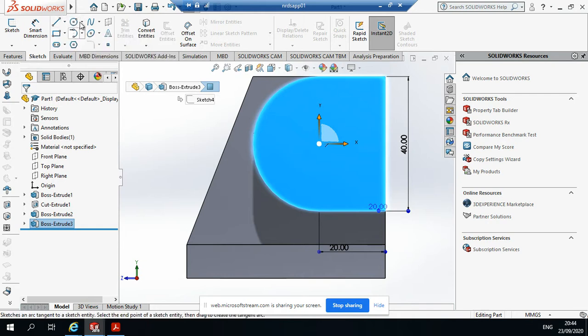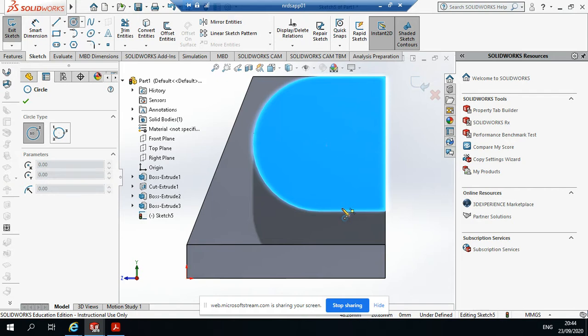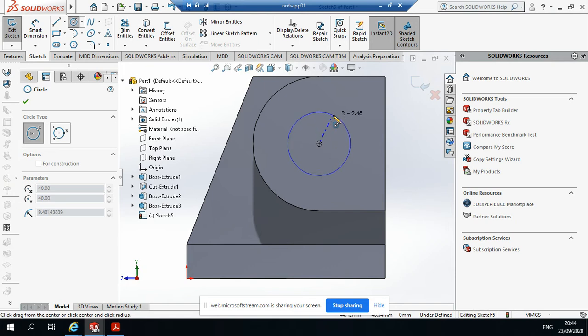This time you want to use a full circle, so select this circle. Okay. If you hover over where you're going to draw a line, SolidWorks will give you a sort of guide. So we know we want our part to be somewhere along this line for our semicircle. We also want it to be in that line there. So SolidWorks will actually give us the point once we've played about with it a little bit, dragged over the lines where it's going to be. So we're happy enough that it's here on that point that we want to draw our circle.